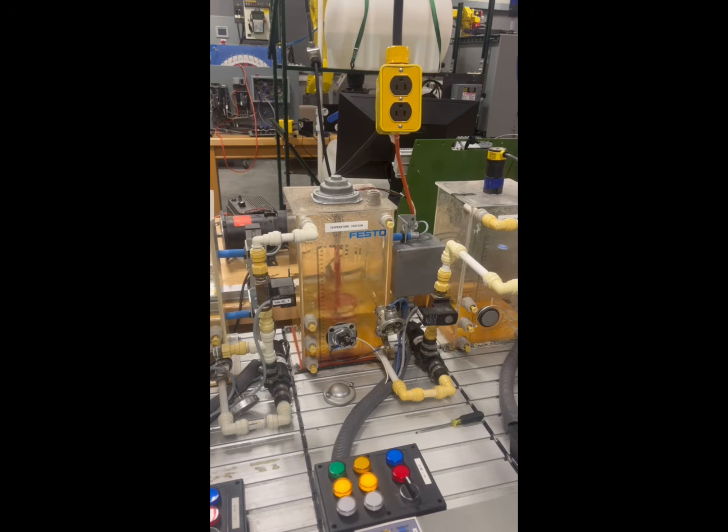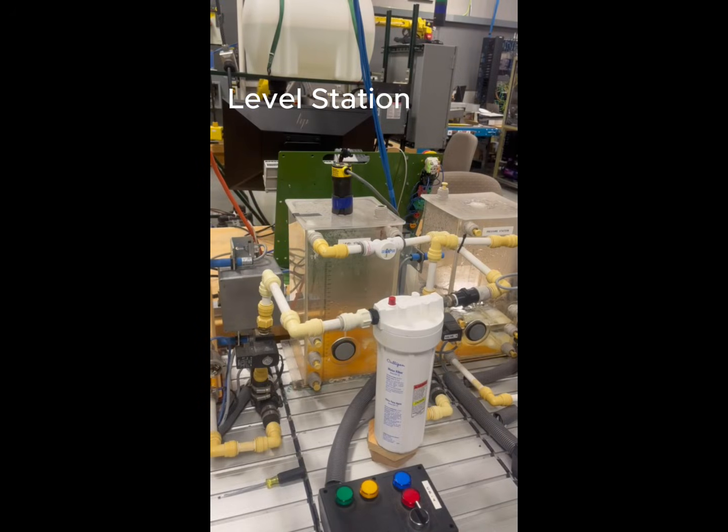When the temp station is done filling up, the heating element in the mixer will kick on until it reaches a good temperature set point that's adjustable through the HMI. Once the temperature station meets the criteria to send water to the level station, it will fill up to its desired set point. The level station will also maintain its set point even if it's sending water over to the pressure station.